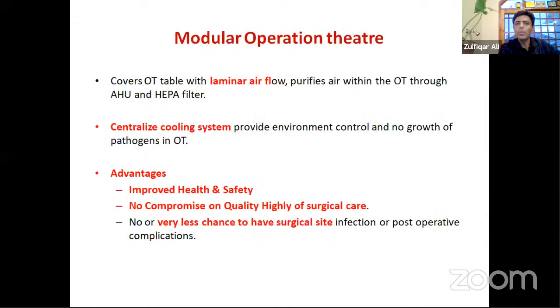Now, coming to the different operating rooms that are in vogue nowadays, we have the modular operation theater. In a modular operation theater, we have the OT table, which has a laminar airflow. The laminar airflow purifies the air within the OT through air handling units and the HEPA filters. So we have a centralized cooling system. We control the temperatures in an ideal way, and it has been seen that if we are using modular operation theaters, there is minimal or no growth of bacteria in the operating room.